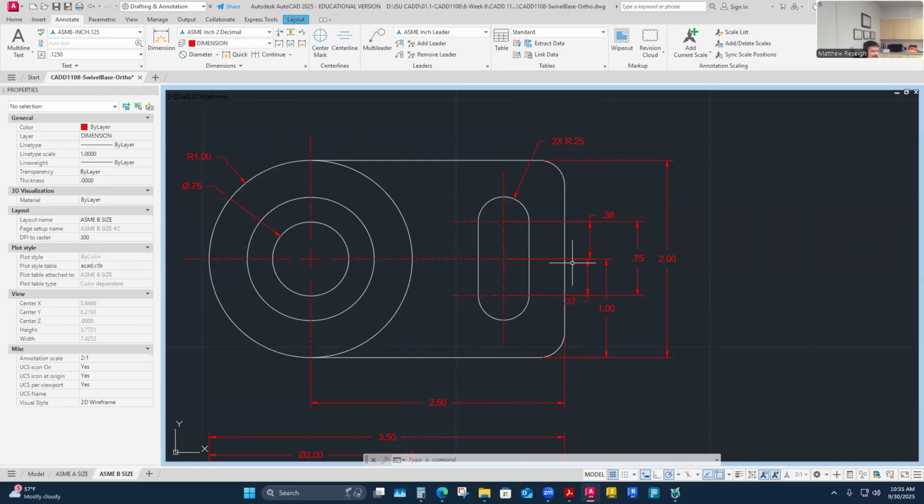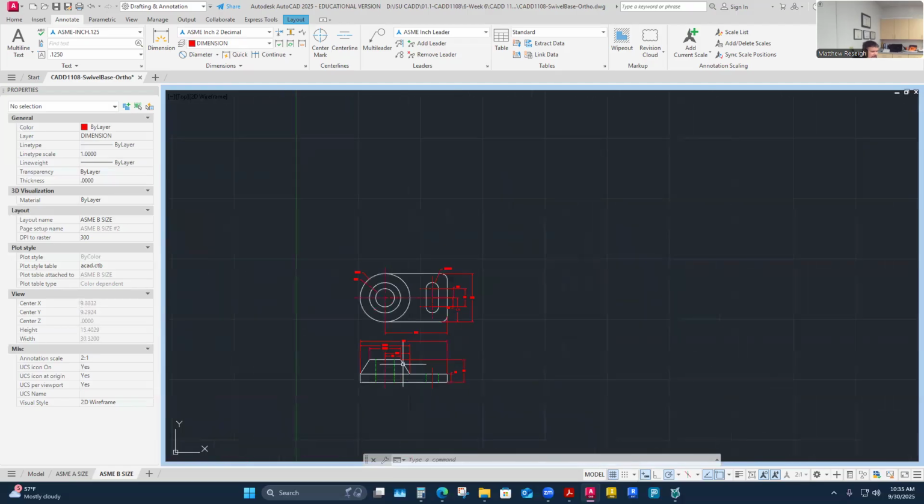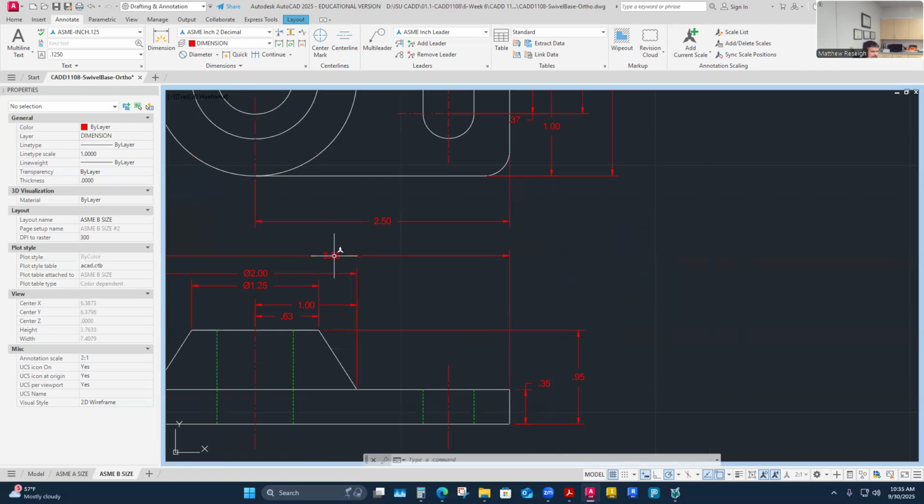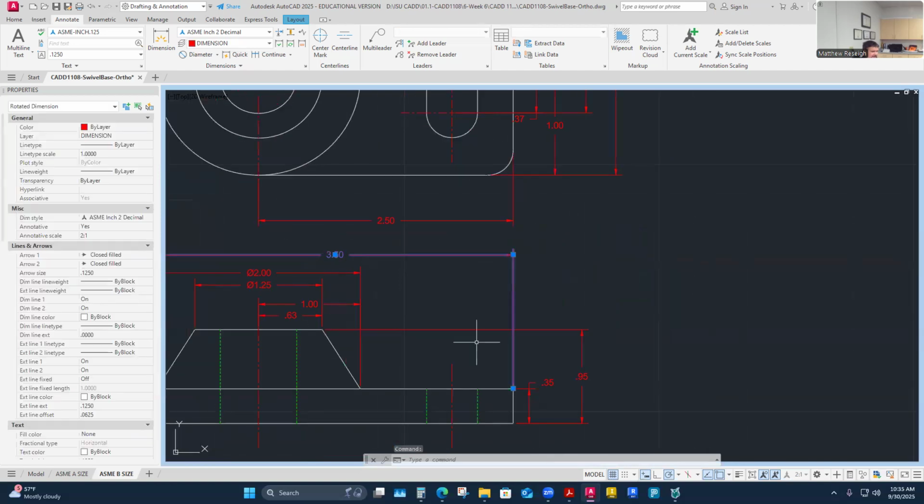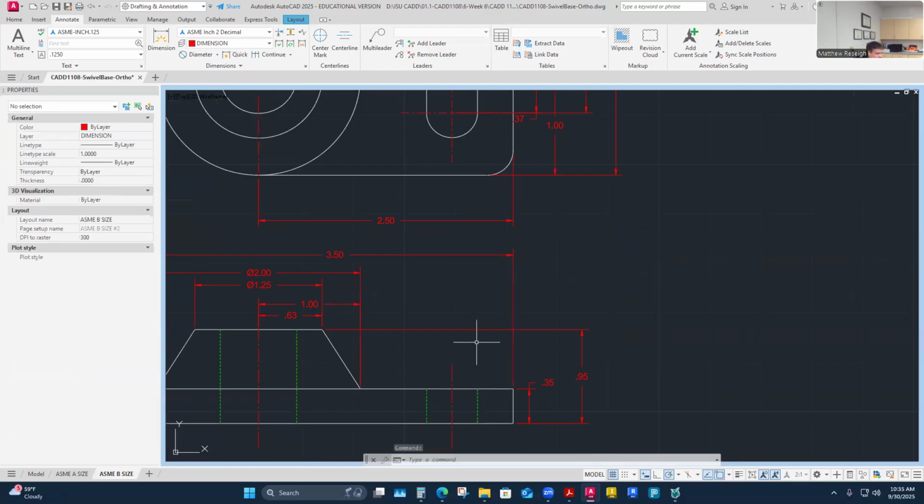I really haven't pulled any dimensions with the right side as kind of a base or a datum. I have this one, but remember, I'm not pulling it from there to there. I'm pulling it from center over. So this is my hold control for that dimension. And if I look down here, I've pulled this one, but I'll repeatedly say these overalls are sometimes going to become reference dimensions and they're not going to really establish a hard datum necessarily. They're kind of informational. So I don't love that one as any kind of real control hold.